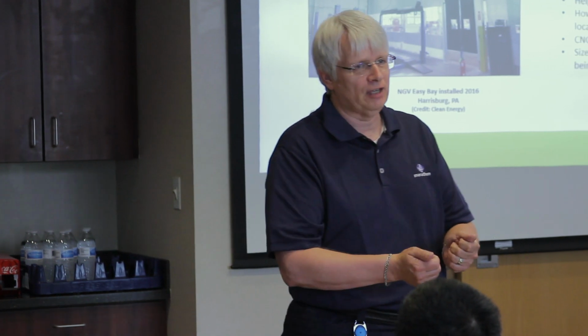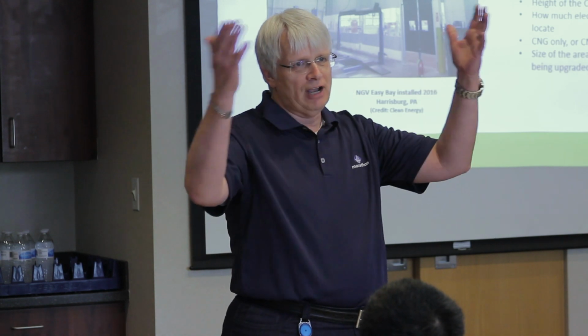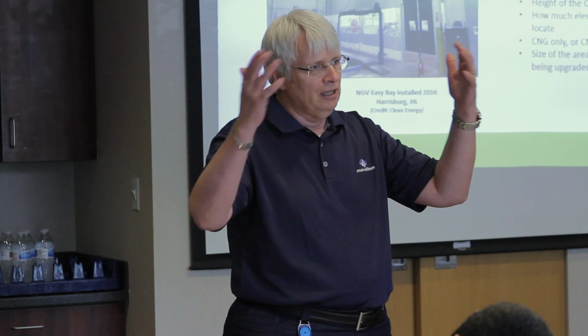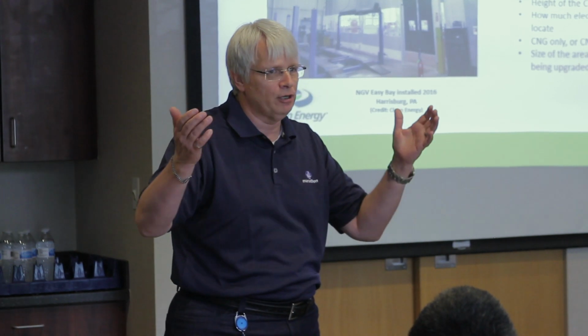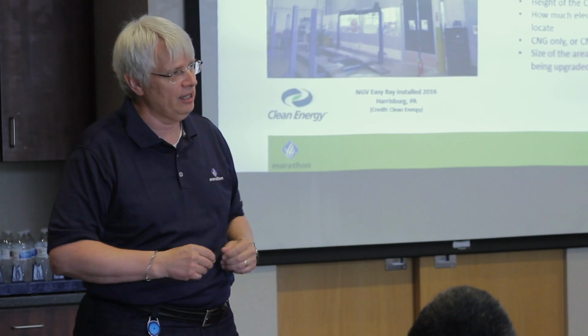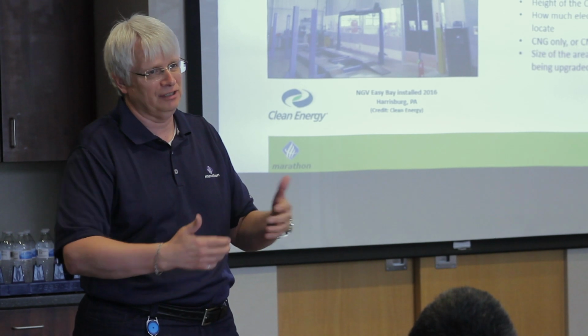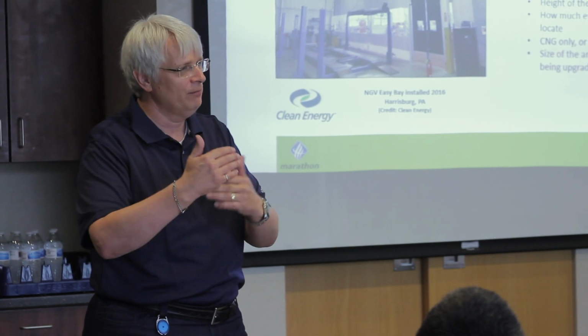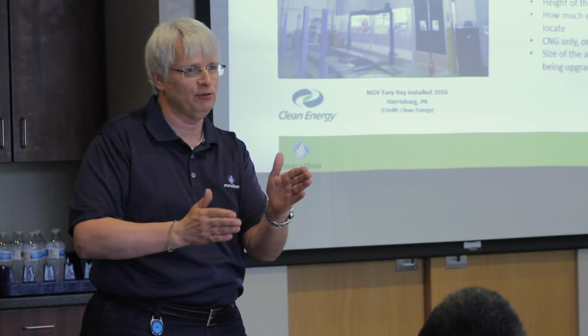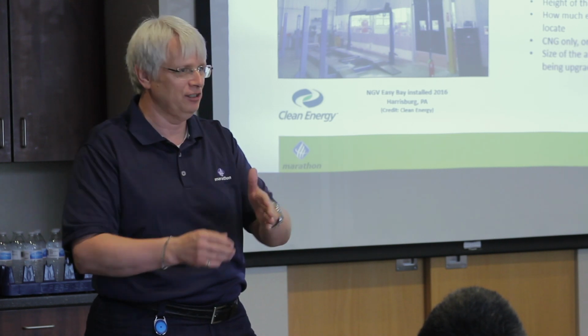So that's one thing. The other is, when you have a release of gas, you want the gas to dilute. Volume helps to dilute that gas. If you dump that gas into a big space, yes, it'll travel further, but it'll also be diluting as it moves out. So dumping it into a bigger space and then exhausting it actually can assist in reducing the amount of time that the gas spends in that 5 to 15% in the case of CNG, or 4 to 76% in the case of hydrogen.